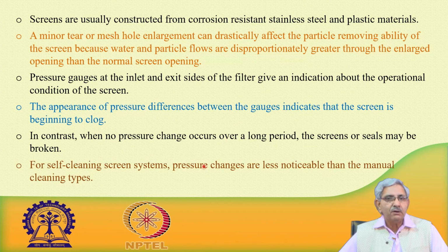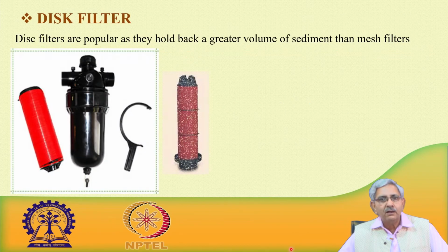This is one important part. For the self cleaning screen, the pressure changes are less noticeable than with the manual cleaning type. So, one can use the flowing water as such, or when there is a lot of sediment or sand deposited on the candle, then one can clean it.